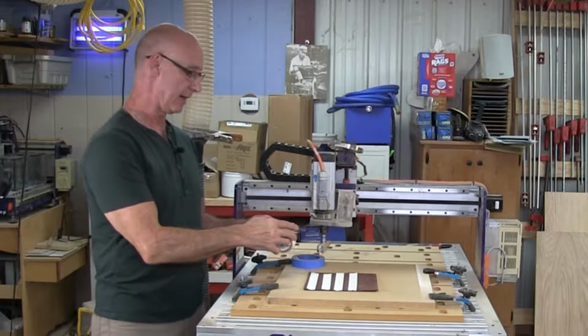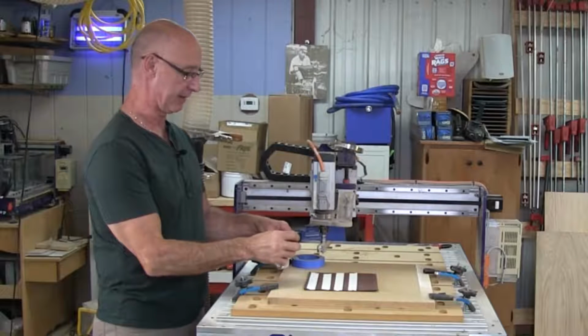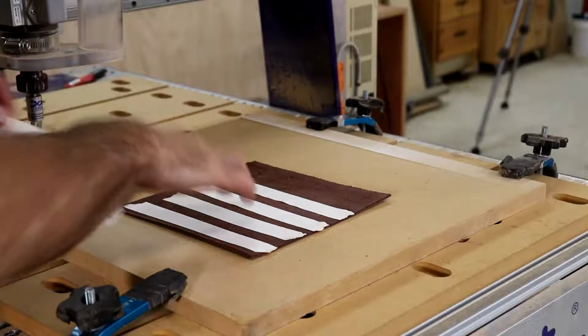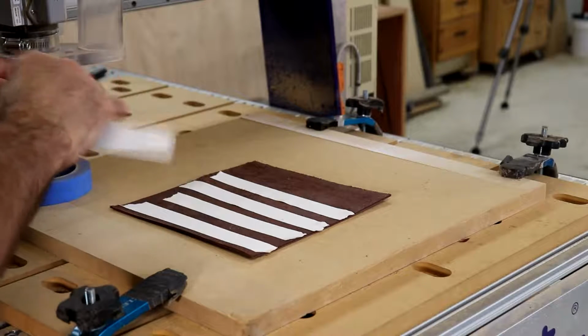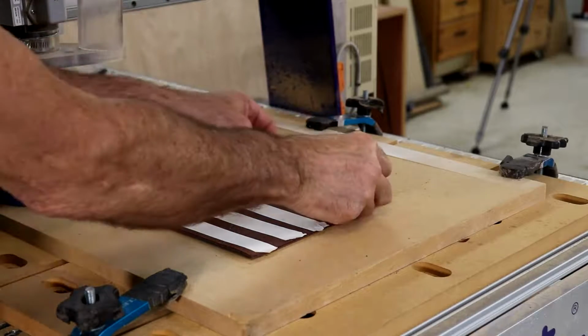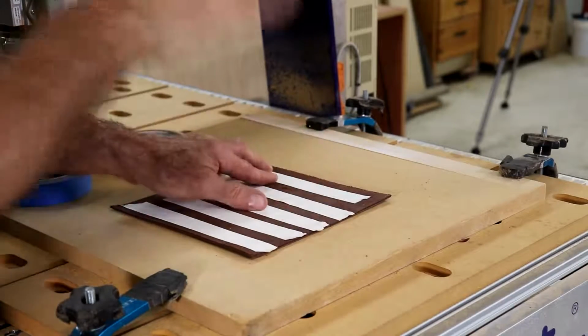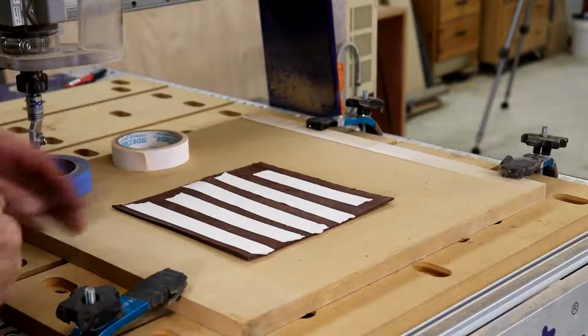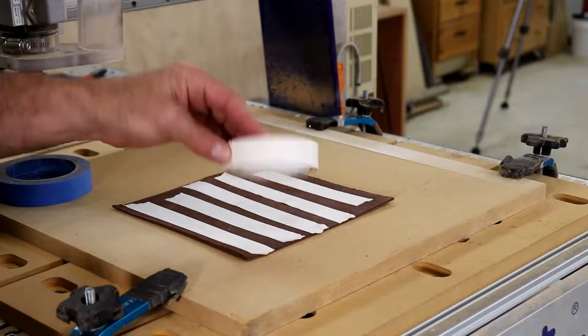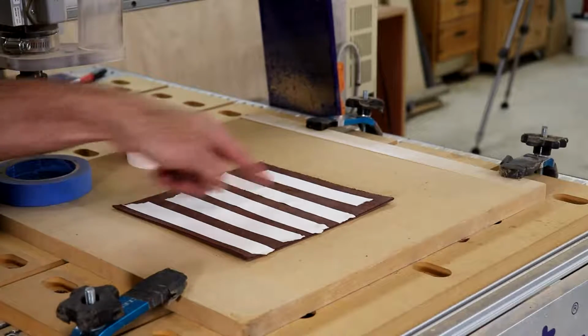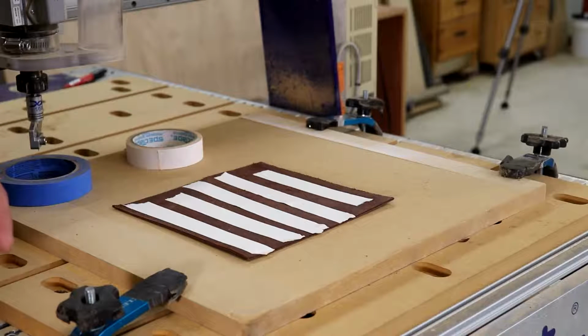When you're ready to put leather onto your spoil board, we can't use the conventional hold downs. We need something that's going to secure it in the middle. I've tried spray adhesive, and that leaves stuff all over the leather that's really hard to clean up. Double face tape works really well for this. I'm positioning the tape less than an inch apart.